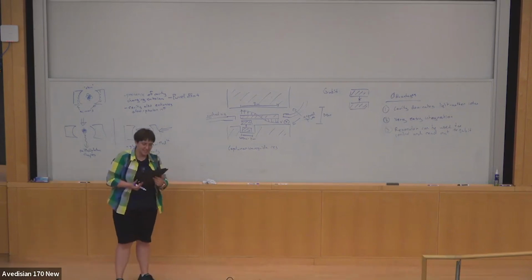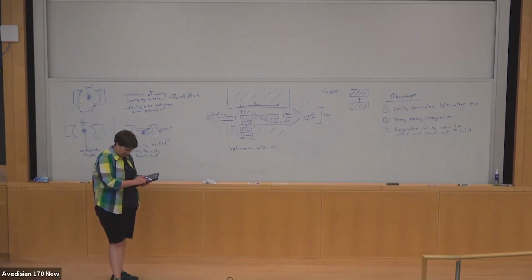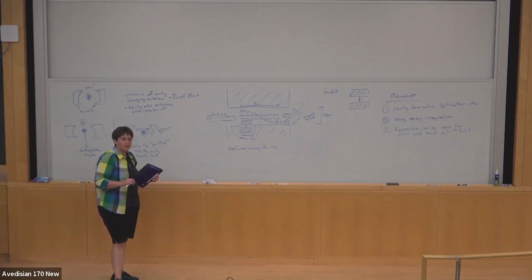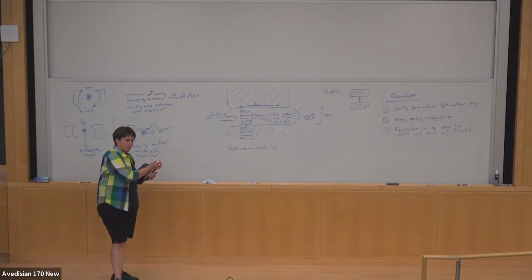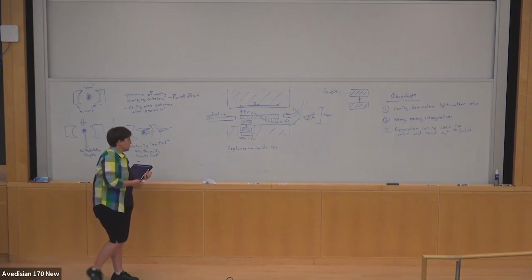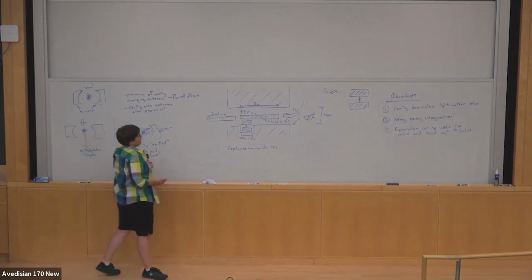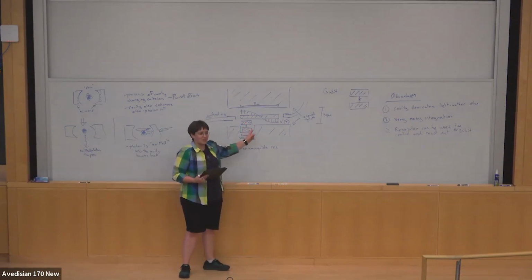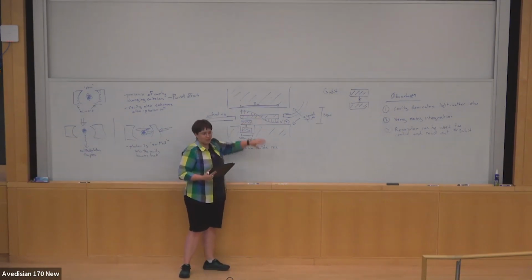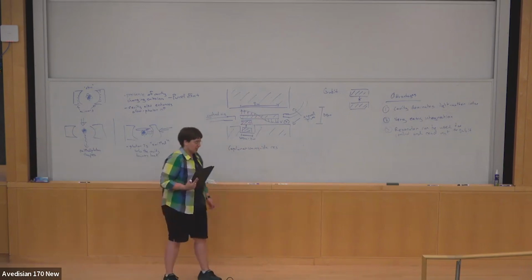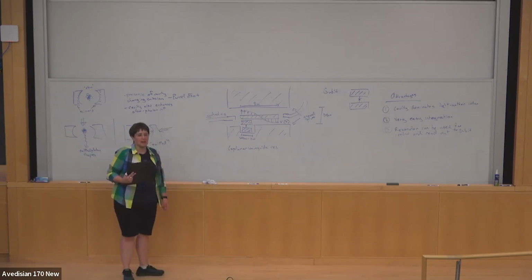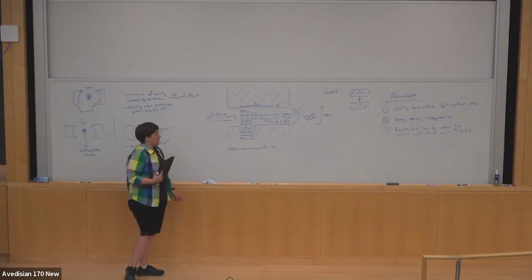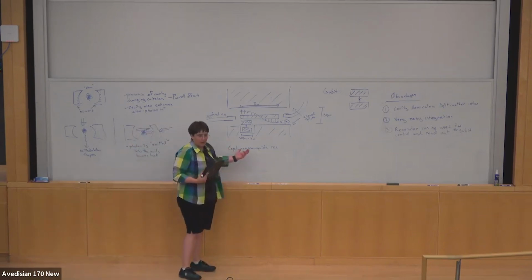So I think you're making the statement that you have to put the qubit at the end of the center pin because of the electric field profile. I'm just thinking, can you actually excite a higher resonator mode to not have a node in the middle of the resonator? Yes. So early on, people didn't realize this trick, and so they used the second harmonic mode and put the qubit in the middle. And it turns out that that's just non-ideal from a microwave hygiene point of view. The other thing is it's very non-compact.